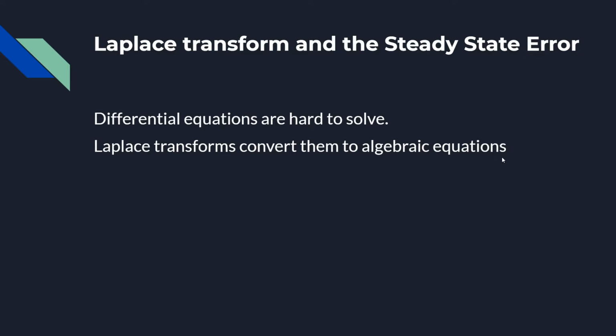If you take a differentiation in the time domain, which is d by dt, once you do the Laplace transform, which is the Laplace domain, the S domain or the complex frequency domain, it becomes S into whatever function you were differentiating.